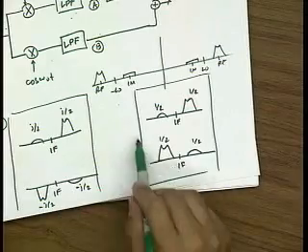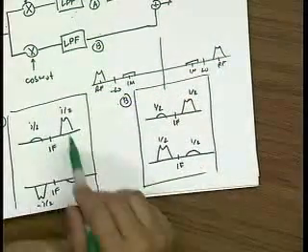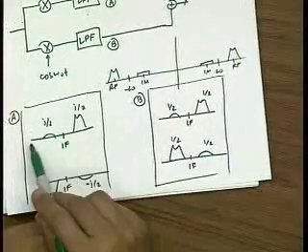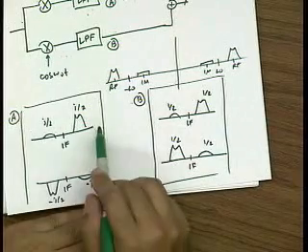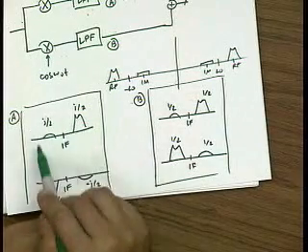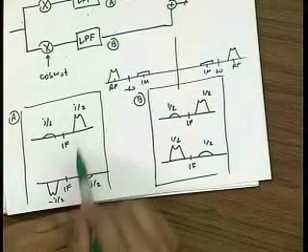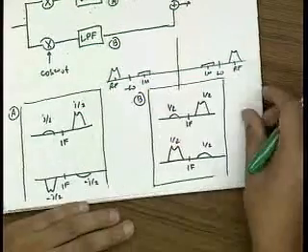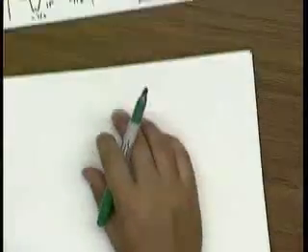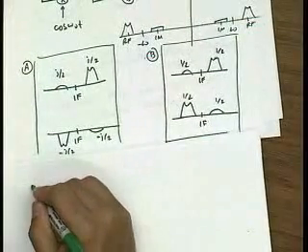On the other hand, if I put a phase delay on A, remember, the phase delay affects the negative frequencies differently from the positive frequencies. So it multiplies by plus j in the negative frequencies and minus j in the positive frequencies. That would actually flip things around in a way that would make things favorable. Let me show what happens when I flip things around. This is going to be at point C.